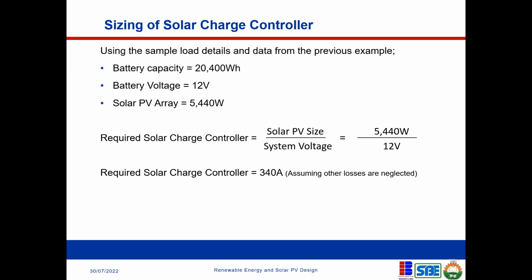So when you say system voltage, what do you mean? If using more than one battery, for example, is it the combined battery voltage? Yes, the combined battery voltage, please. Don't forget to change the battery voltage here. The system voltage should be the inverter voltage. That's the inverter voltage. Actually, that's the inverter voltage, exactly.